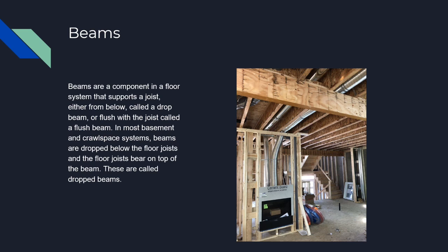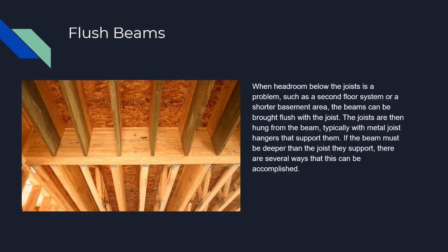Next, we'll talk about beams. Beams are a component in a floor system that supports a joist, either from below, called a drop beam, or flush with the joist, called a flush beam. In most basement and crawl space systems, beams are dropped below the floor joist, and the floor joists bear on top of the beam. These are called drop beams.